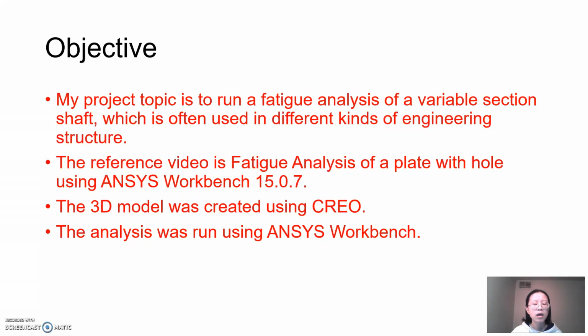The 3D model of this shaft was created using Creo. Then I imported these IGES files into the analysis software ANSYS Workbench to run a fatigue analysis.